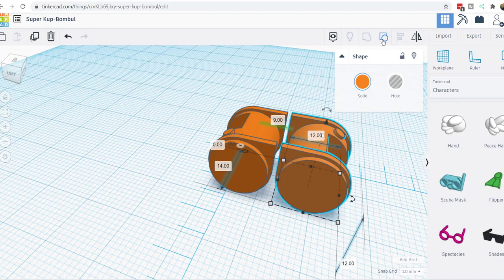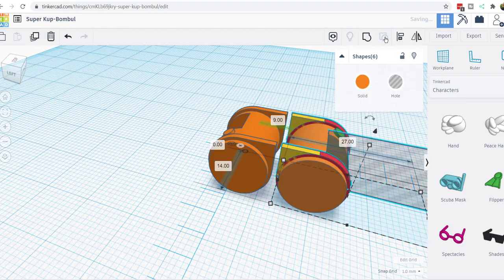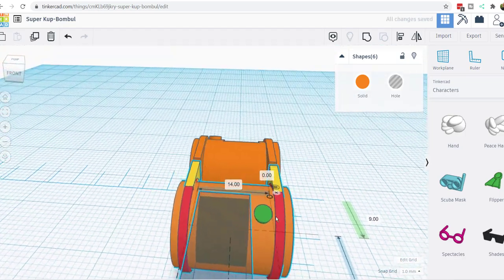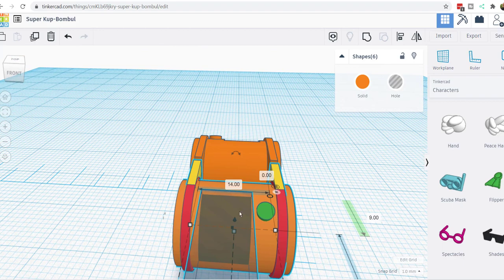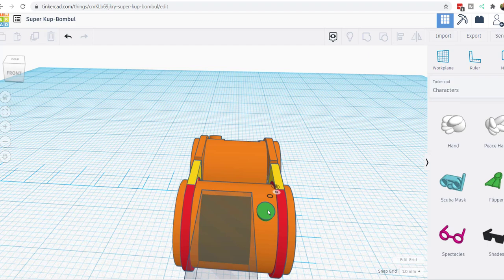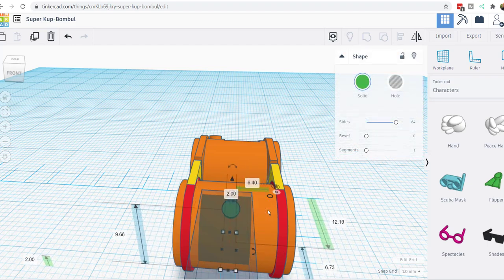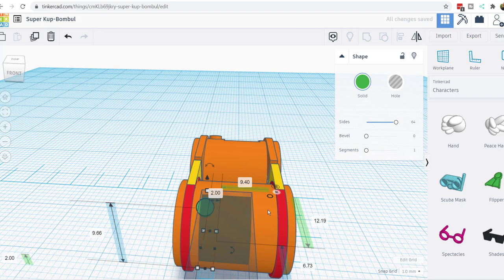We're going to ungroup the parts, and then we will select it again and continue to ungroup until we see our hull and our fuel cap separately. Now what we can do is take these two items and move them individually. So the green cap is now selected. We're going to move that off to the left.